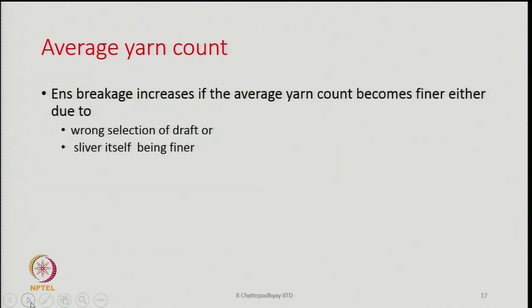Average yarn count: end breakage increases if the average yarn count becomes finer, either due to wrong selection of draft or the sliver itself being finer. This may happen in industrial situations, that sometimes the draft may go wrong or the sliver itself has become finer due to some reason during the manufacturing of the sliver, maybe something has gone wrong in the draft selection on the carding machine or draft selection on the draw frame.